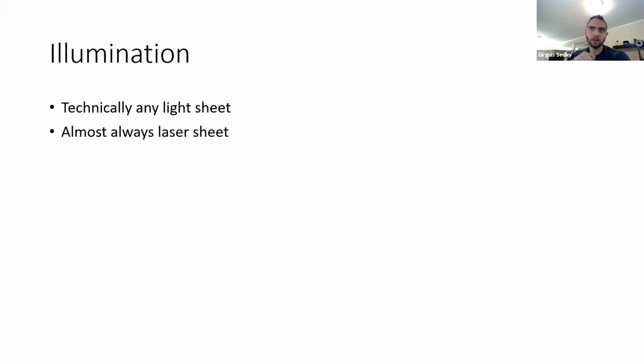First of all, lasers are very consistent in their illumination intensity, so you're not going to get lots of variation in the amount of light in your light sheet, which would be a problem for your experimental data because you're going to get garbage correlations if you have varying intensities in your light sheet. So it's easy to control. Since it's a narrow laser beam, you can easily shape it into a laser sheet with a thin thickness.